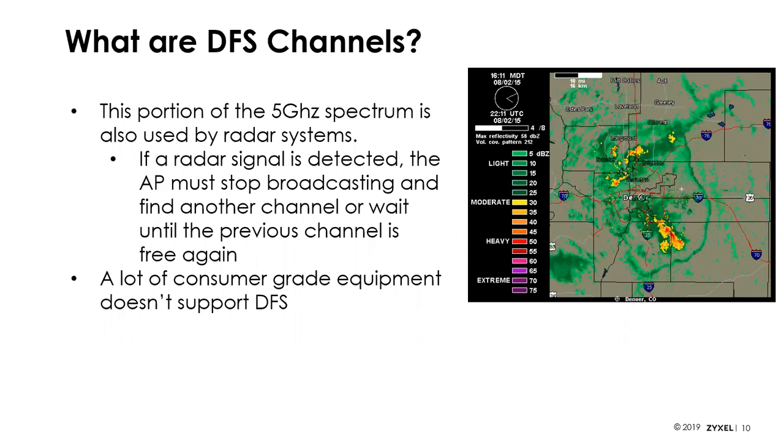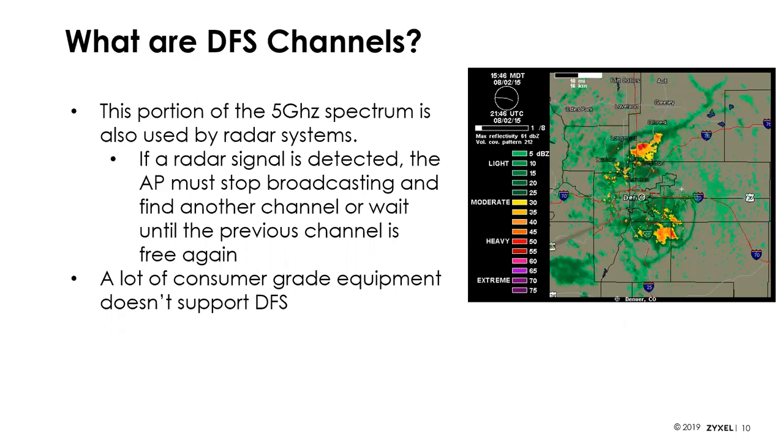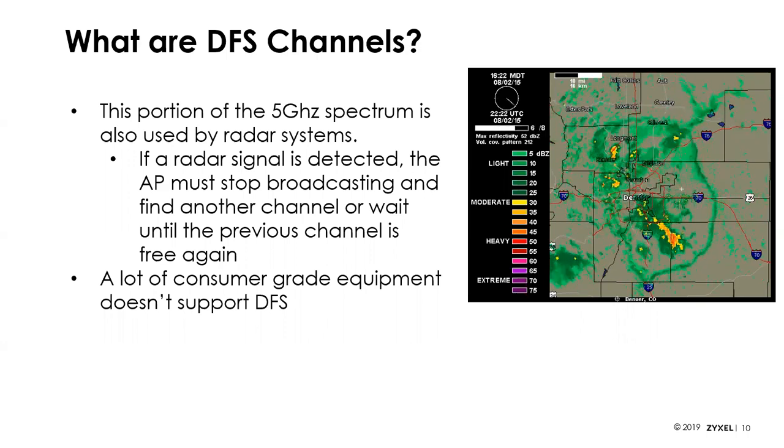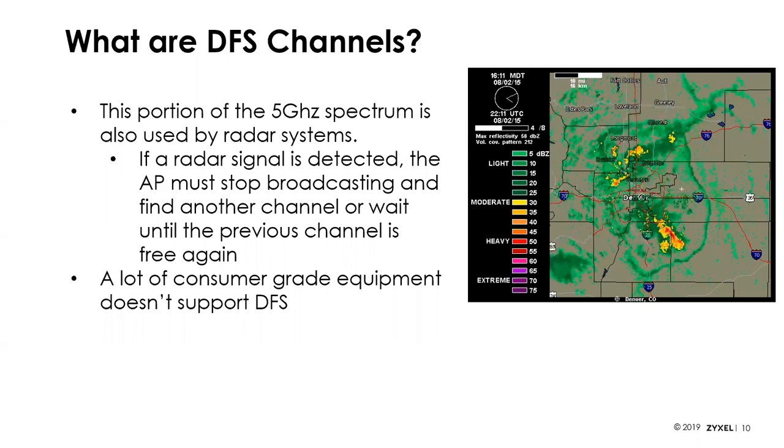broadcast. But one of the challenges you run into is, based on weather, based on what's going on, the channel may be good for a while, and then it will experience some noise on those channels that it'll detect as being legacy usage. And so by FCC rules, you have to stop using that channel. So one of the problems you run into with this is if you're using these DFS channels, it can cause you to occasionally be thrown off your network, and it can take 30 or 60 seconds before you move to a new channel and can resume connecting again. So a lot of users obviously don't like to be disconnected at random times from their network.